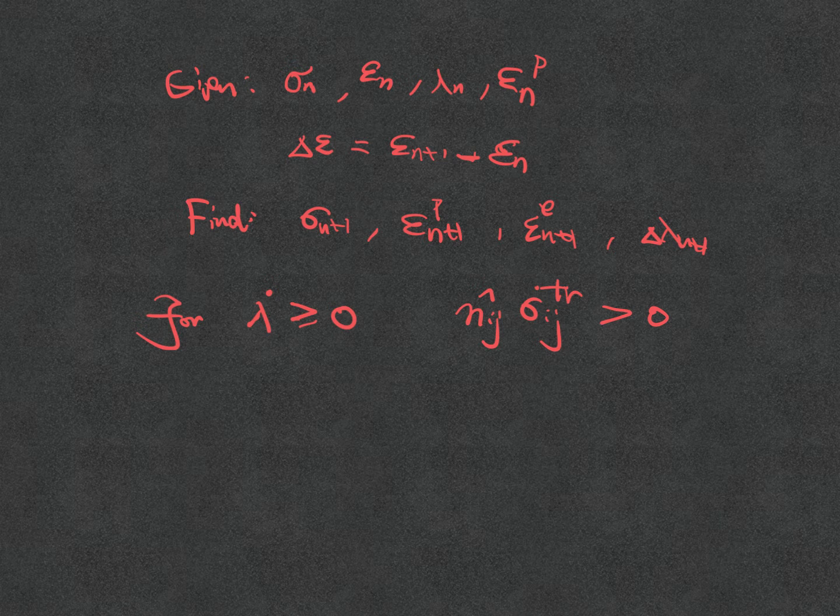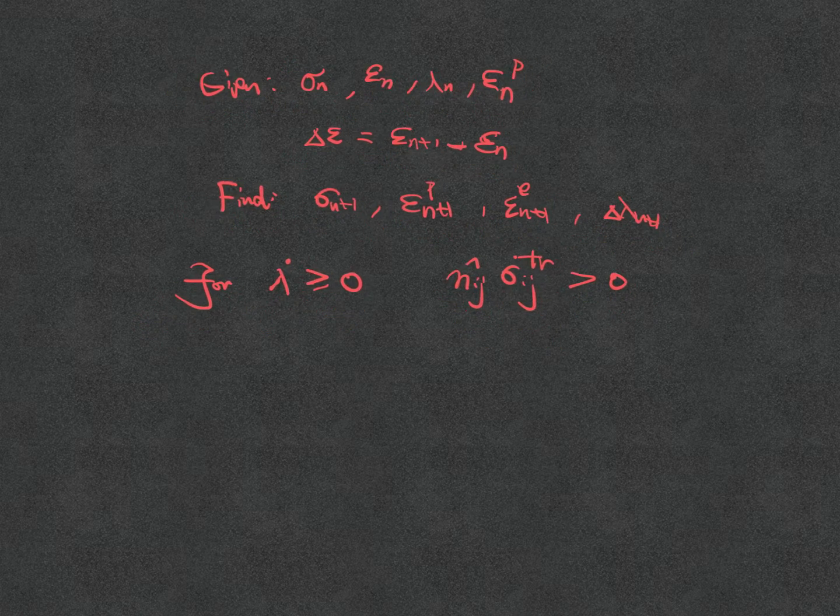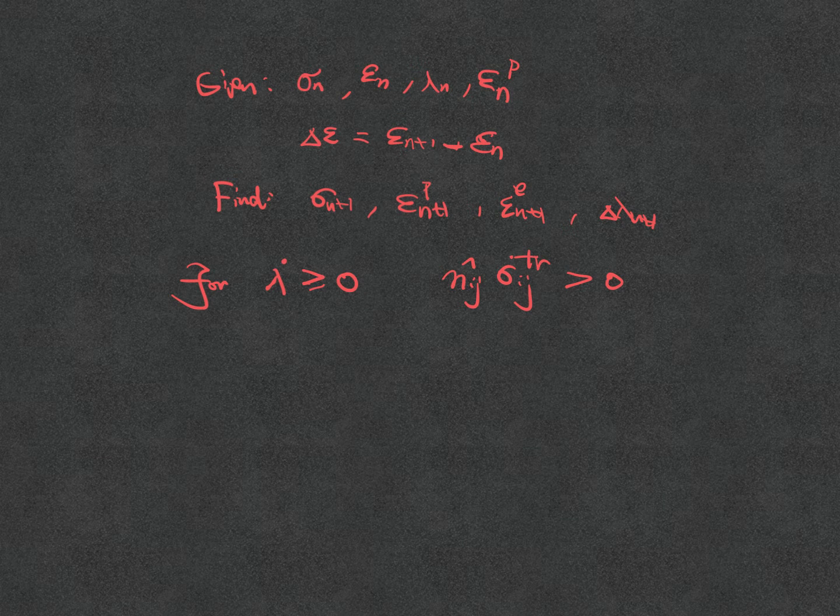This is actually coming from writing in the computer. We actually don't have a continuous strain or continuous stress as a function of time. Instead, we have multiple discrete time steps. So from the previous time step, I have a yield surface, f of sigma, n, kappa equal to 0.